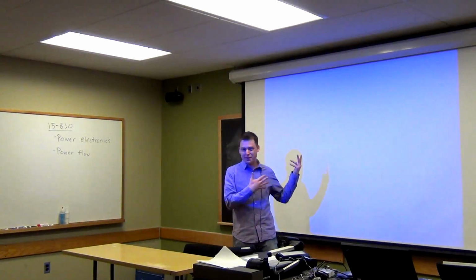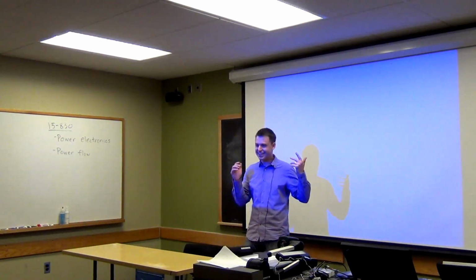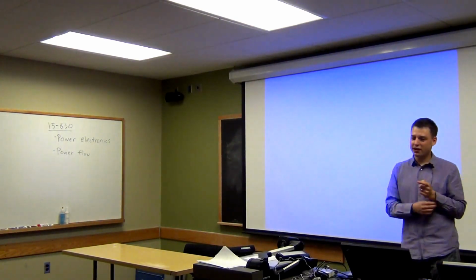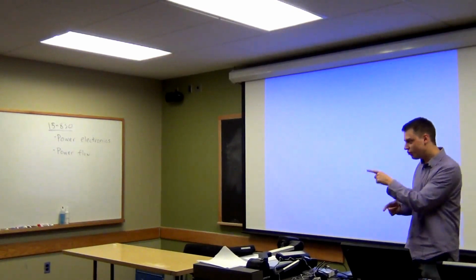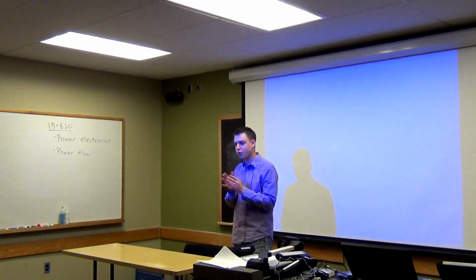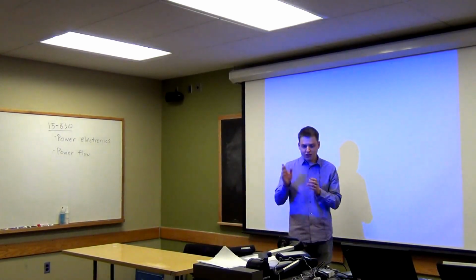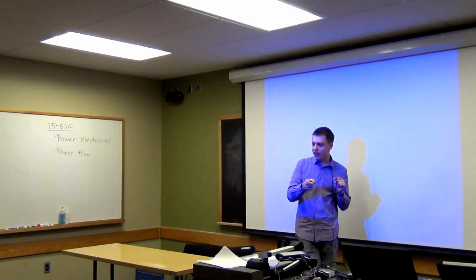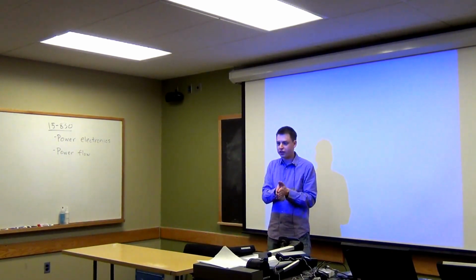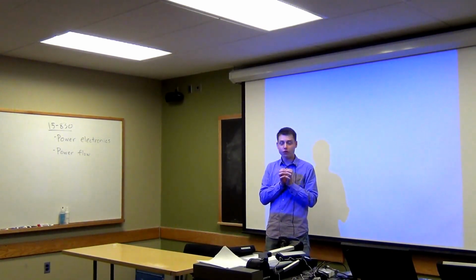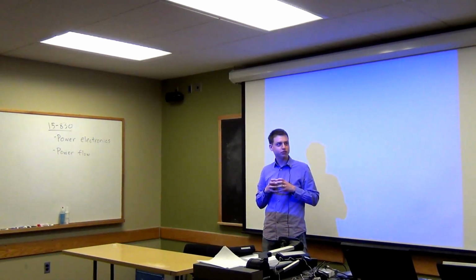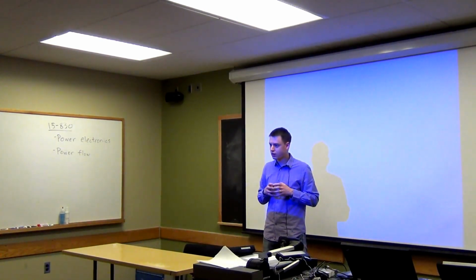Does anyone have any questions about what you just saw? Yeah? Should the max be 120? Right, so this is what we mentioned before in class, remember. The voltage in an AC circuit is 120, but that is actually talking about root mean squared voltage. So that's if you take that whole signal and multiply it by the root mean squared value of it. So the actual voltage is square root of 2 times that. Yes, square root of 2 times that.